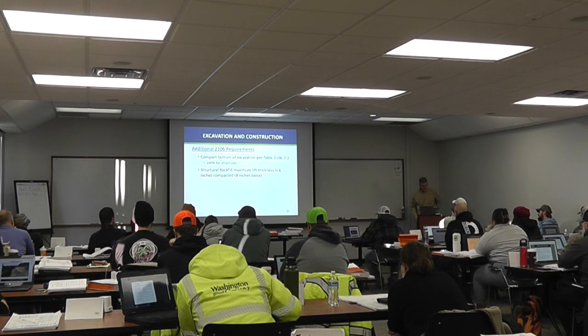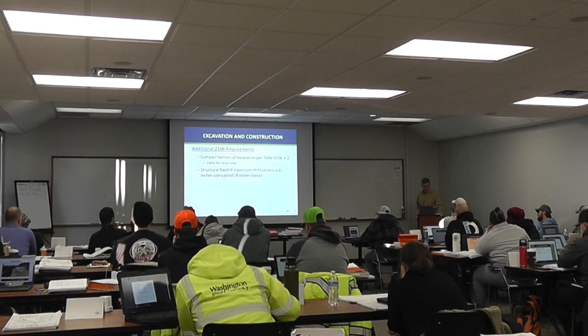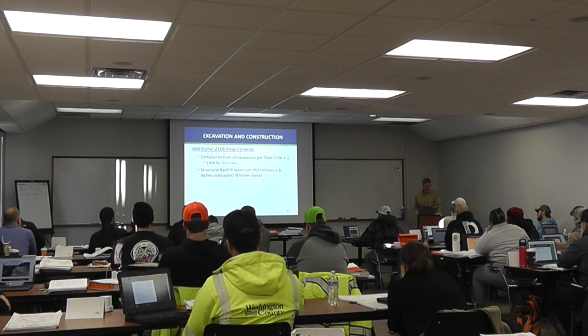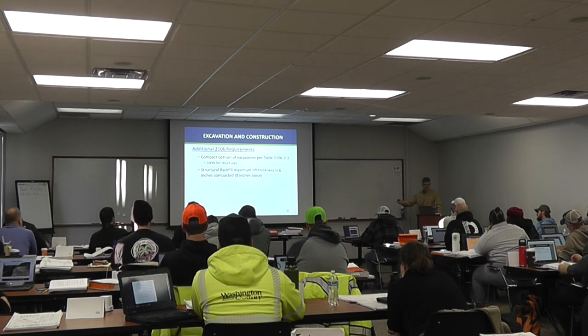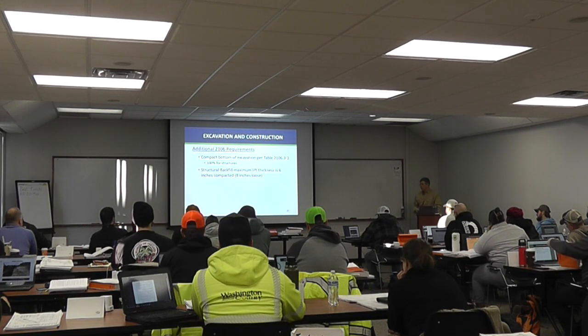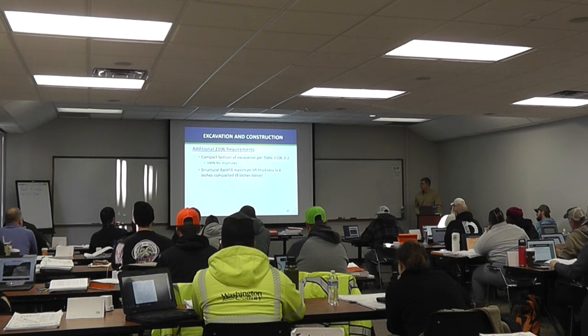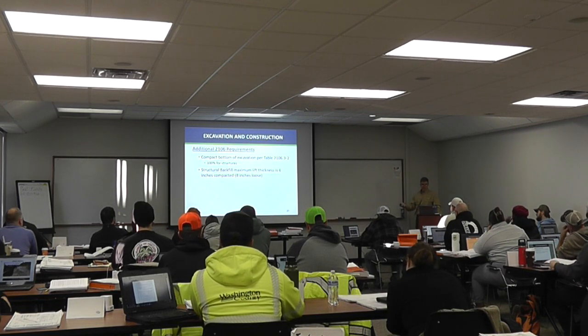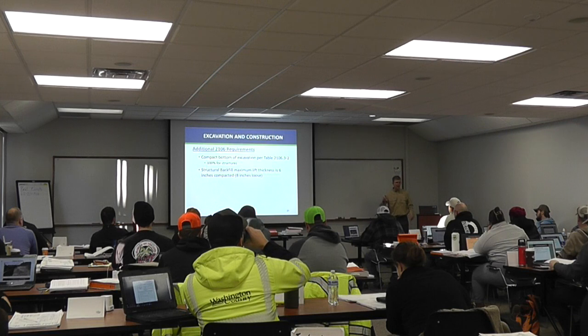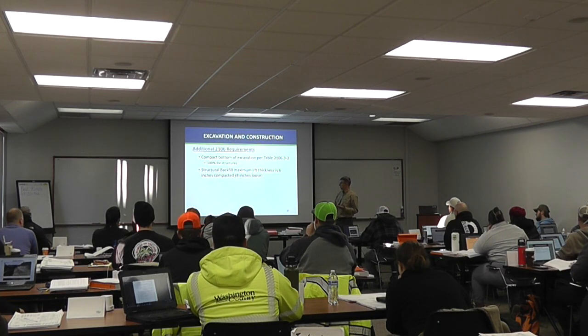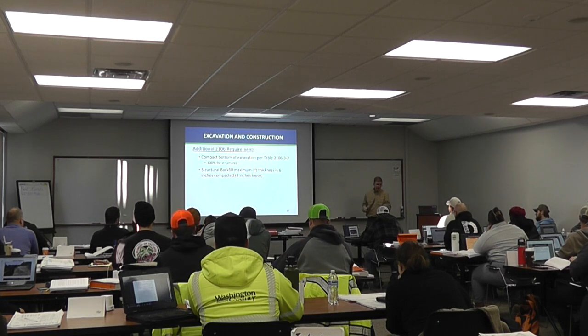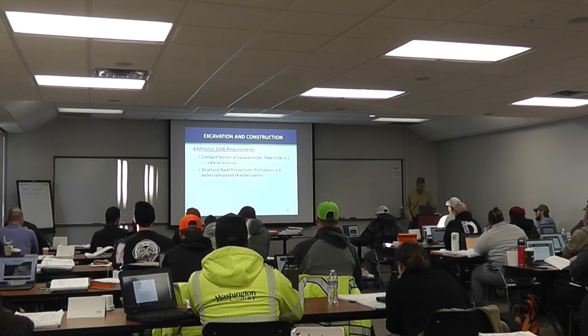So there are some additional requirements in 2106. You compact to 100%, we already talked about that. And then there's a requirement for the structural backfill. The maximum lift thickness is 6 inches compacted or 8 inches loose. So they put the loose material down and they run their compaction, and it should be no more than 6 inches. That's not just something that you as the inspector say, you never go over 8 inches. Well, it's in the spec. So just be aware of where it is in the spec, and then the contractor doesn't have a.